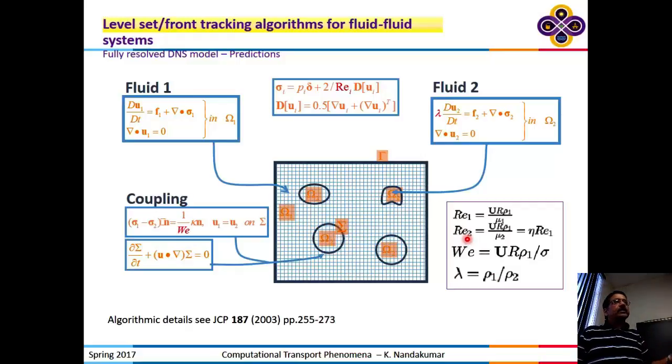Again, people have studied in the last 5-10 years direct simulation of these with maybe 300, 400 bubbles. But in a typical bubble column reactor, you'll have 1 billion bubbles, very, very tiny bubbles, right? So we cannot use these DNS tools to solve industrial scale problems. So that's an issue that we're going to address next. These can be useful for extracting information about the interaction between the fluid and the bubble, fluid and the particle, and use that information for the so-called coarse-grained models, mesoscale models.